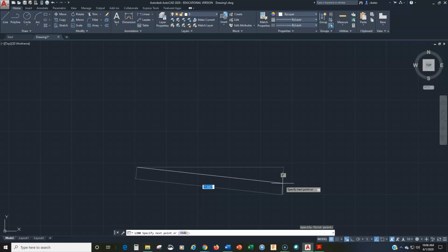And so in this case, I want to go 5 to the right, so I'm going to type in a 5, and then I'm going to hit tab, and I want to go at an angle of 0 degrees. That's due east, right? If I hit tab again, it'll take me back to the 5, and you'll see, right? I didn't have to hit tab, but we went there.